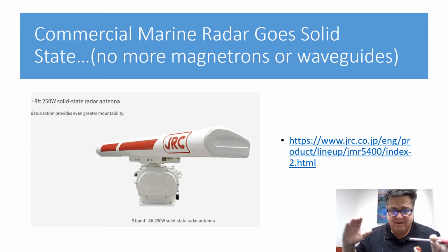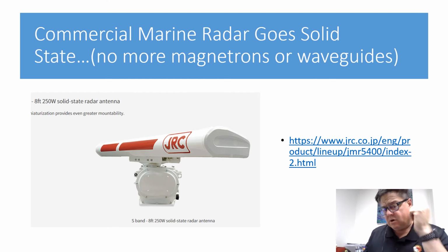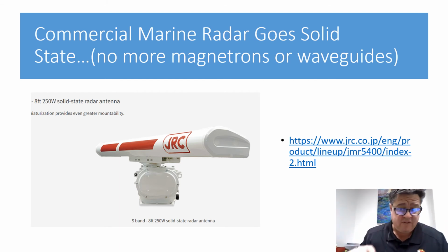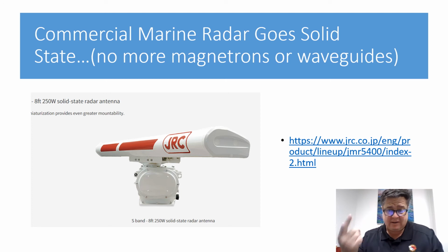The solid state radar comes out of that board, and it generates it on a computer board. It generates the radar energy in a coax cable, and it comes flying out into the back of this emitter, and it comes bursting out of the emitter in the timing that we want it to have in order to create a wavefront. That's what we do with phased array. But with this unit here, we just have one big board putting out radar and slide it down into a slotted waveguide and let it turn around and go.